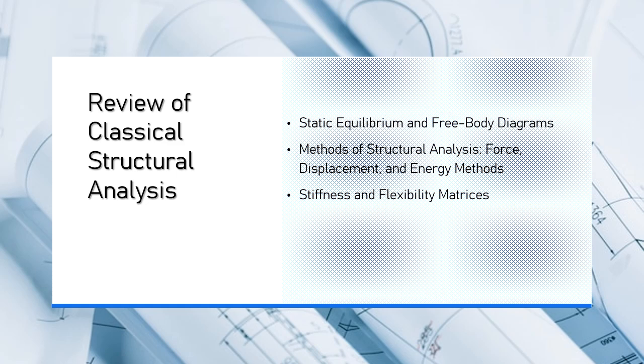Displacement methods. Complex frames, multi-degree freedom systems. Easy to implement using stiffness matrices. Good for large structures. Requires extensive computation. Matrix methods. May be complex for simple systems. Energy methods. Indeterminate structures with bending or twisting. Provides simple solutions for deflections and internal forces. Requires knowledge of strain energy and may be computationally intensive.